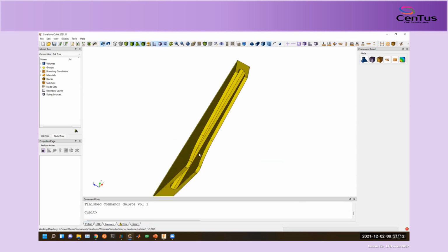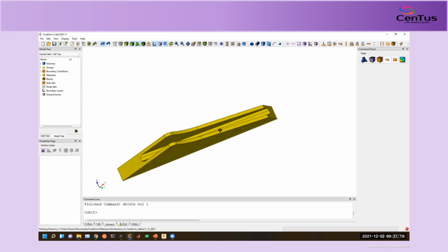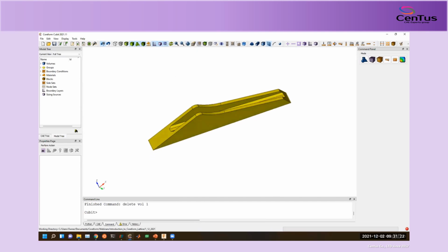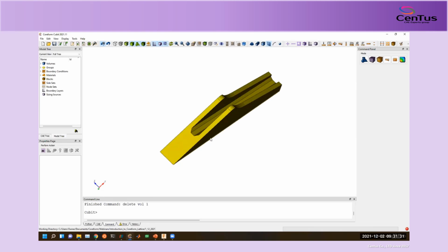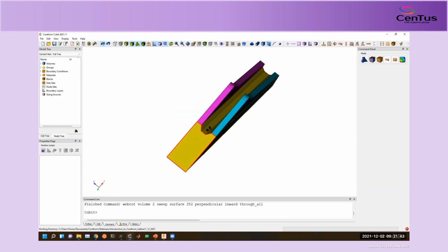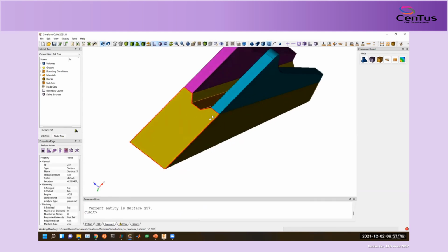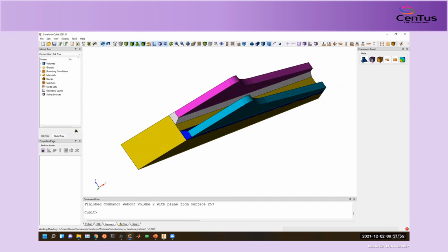We start by working with our lattice structure region. This is a complex region we're going to fill with lattice structures. The first thing we're going to do is cut this into hex meshable sweepable regions. I'm going to first sweep these surfaces through to chop off these top two regions, and then I'm going to slice with this plane here to slice off these two nubs. So these are the regions that are going to dictate my hexahedral mesh.